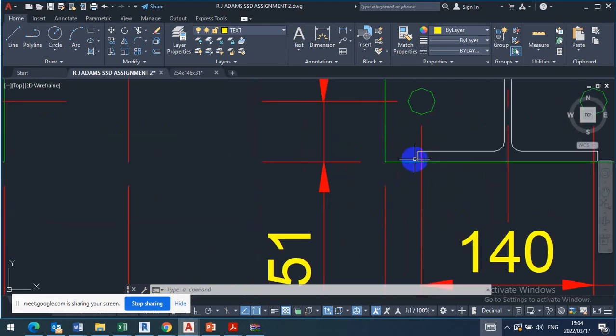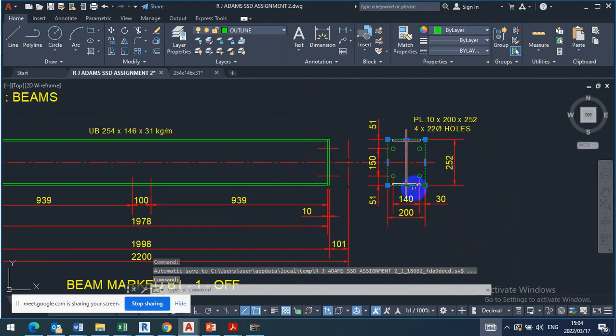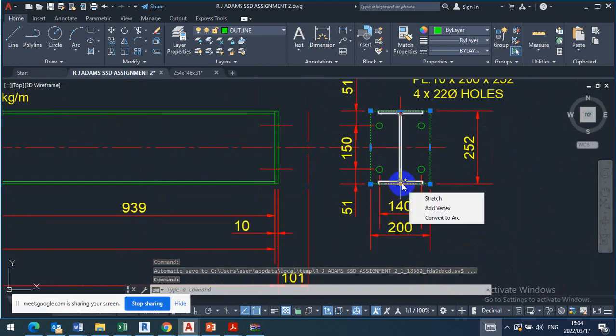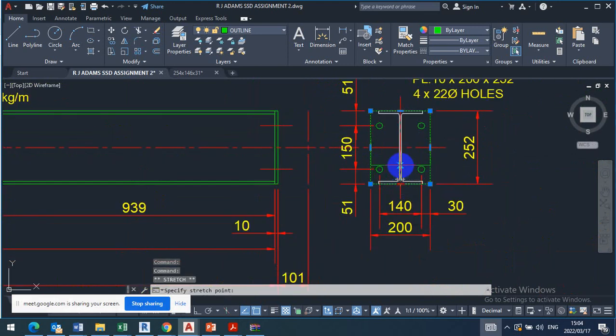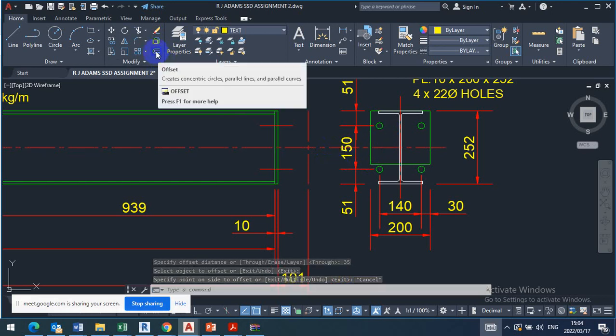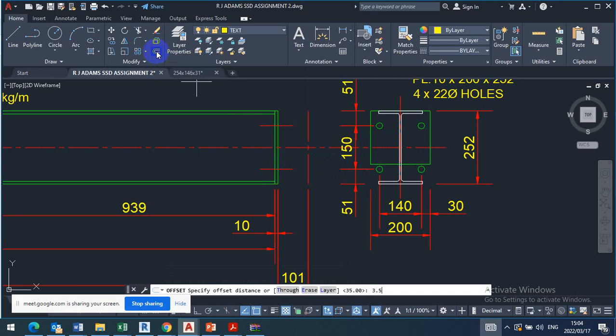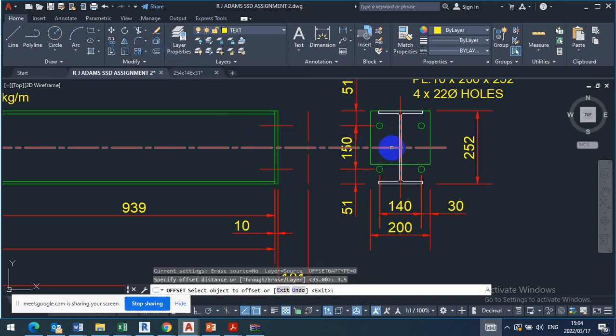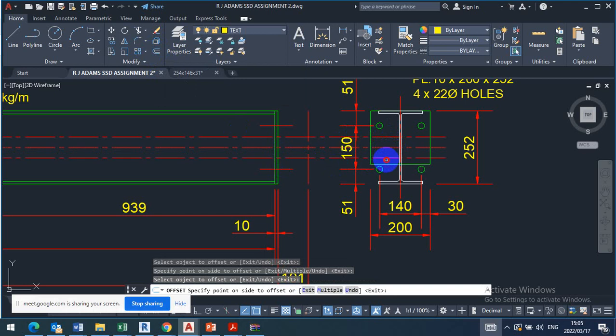Let me show you. I see this is marked at 30. It should be 40. Yes. What I'm saying is let's try to offset the center line. If I offset the center line by, let's say we want to use how much pitch? 70. Then if I use 35, then I say enter. Then I offset this one. But it won't be 35, it's 35 divided by 10. You already scaled it down. Yeah, 3.5. Enter. It's going to be like that.